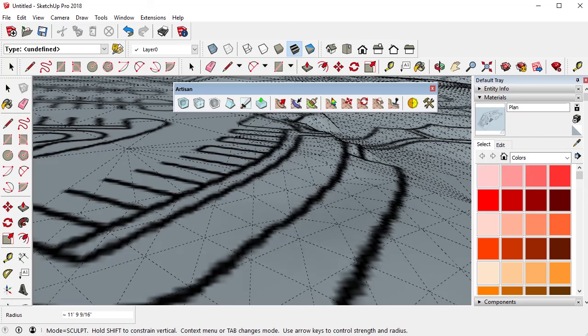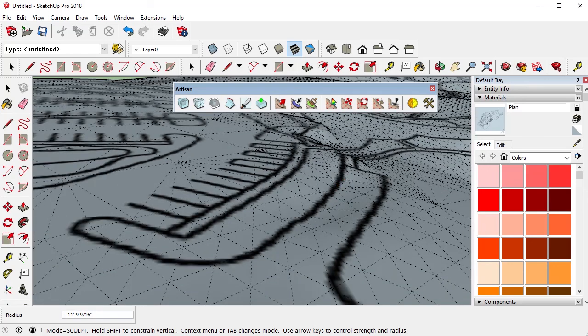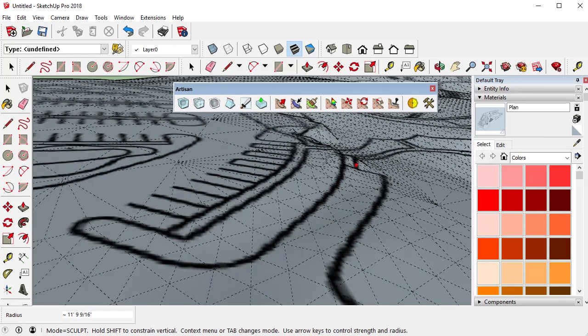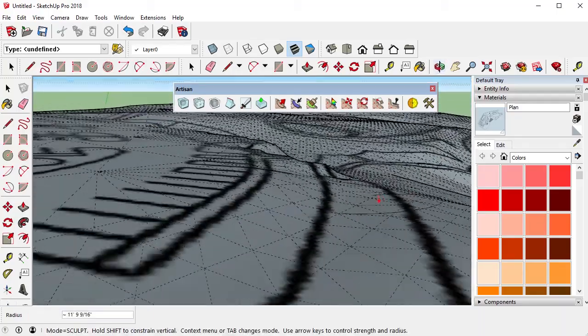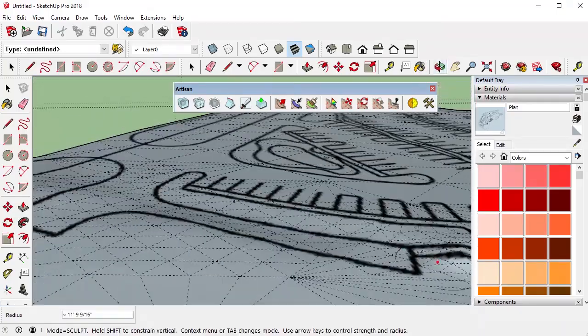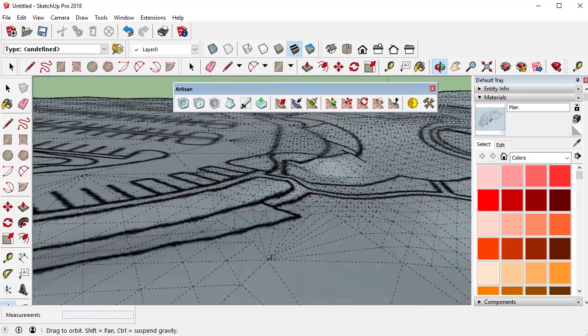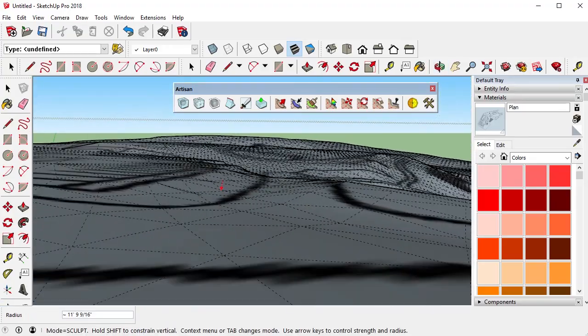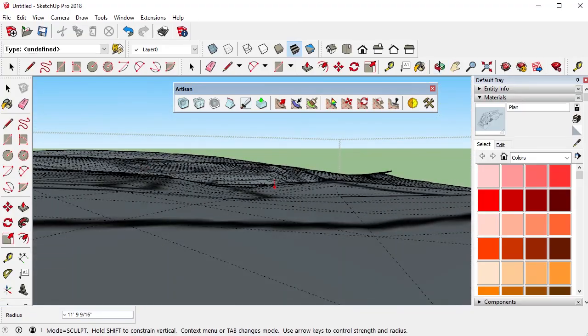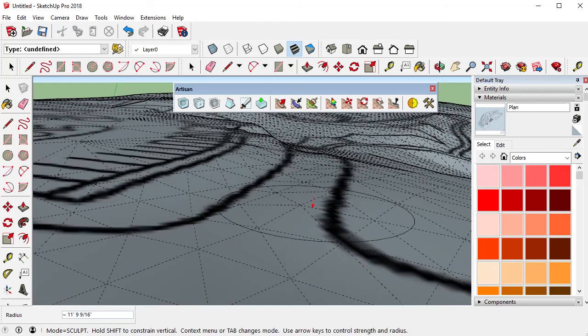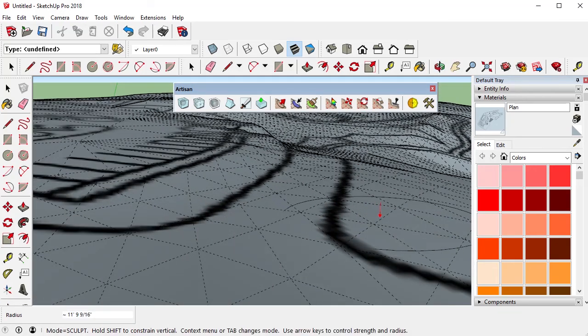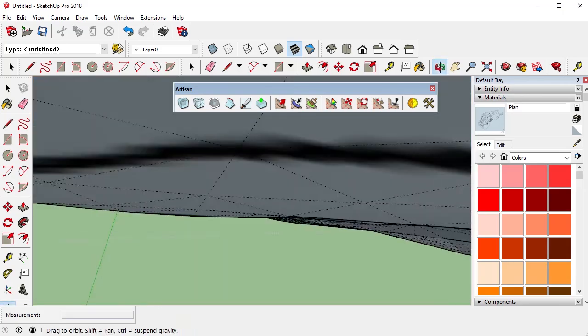Need a little more intensity here. Shape that down on this side. And just kind of like working with clay. Right, that's not too bad. We got some weirdness happening over here. And you'll shape that down. This is the area that's supposed to be picking up that grade between that upper parking lot and that lower path. And I'll go ahead and drop the intensity down, just shape that just a little bit. Maybe I actually want this to be deeper on this side of it.